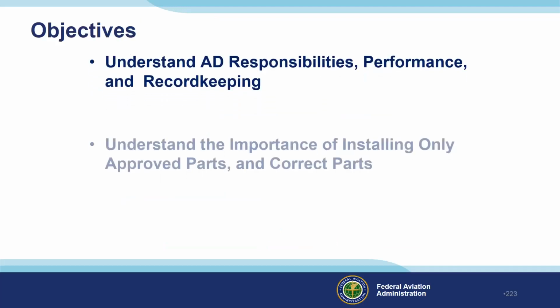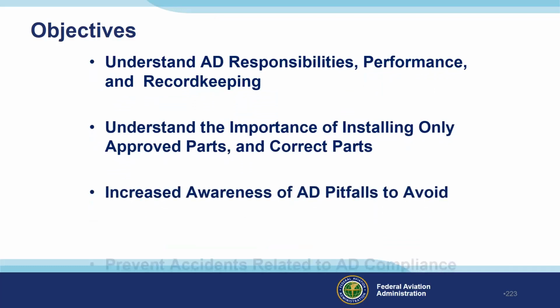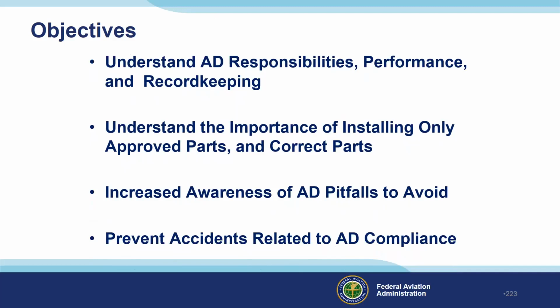I hope we've met our objectives on ADs. We understand the responsibilities, the performance of them, and the record keeping. Understanding the importance of installing only approved parts and the correct part. Remember the oil drain. It was a good part, but it wasn't the appropriate part for that airplane. Increased awareness of AD pitfalls to avoid, and that will now prevent accidents related to AD compliance.